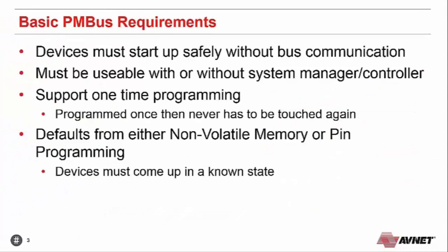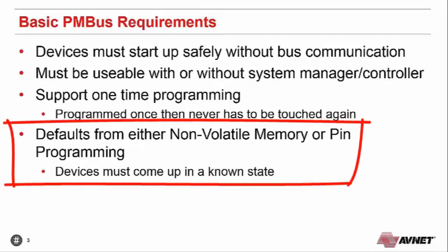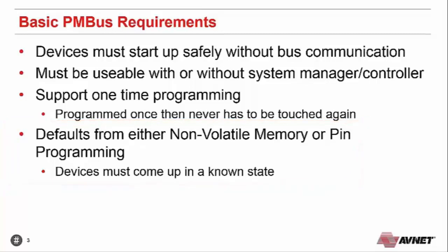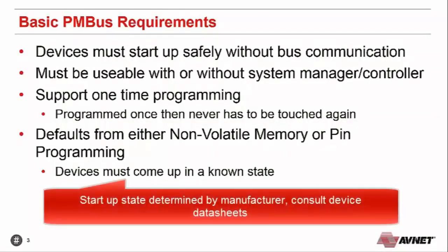So some of the basic requirements of the PMBus: devices must start up safely without bus communication. They must be usable with or without a system manager or controller. They have to support one-time programming, meaning it's programmed once and you never have to touch it again. And when it first comes up, it has to default either from non-volatile memory or from pin programming. What that means is devices must come up in a known state. So basically these things just ensure that if you power up the device without having loaded anything into it, you know what it's going to power up as.